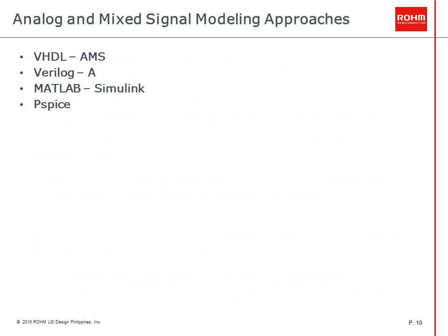Analog and mixed signal modeling approaches. VHDL-AMS and Verilog-AMS allow modeling of discrete and continuous time signals or a combination of both. All the aforesaid HDL languages can represent AMS systems at a higher level of abstraction by bringing down the simulation time while providing the intended functionality of the design. The following sections describe the process of modeling in each of the languages and finally a comparison of all the available modeling options to give a clear understanding of the pros and cons of each language.